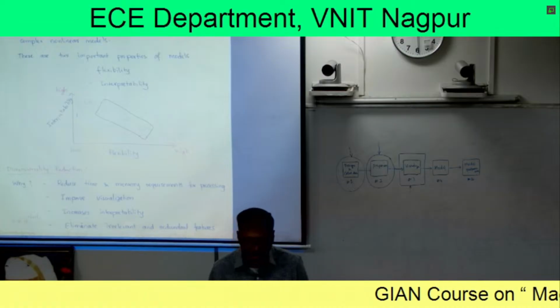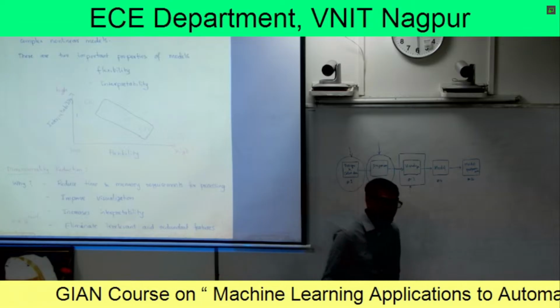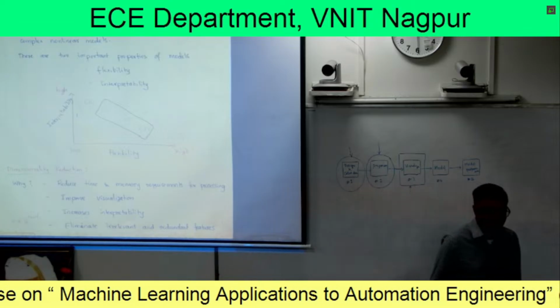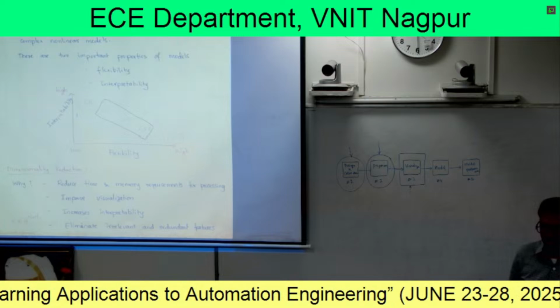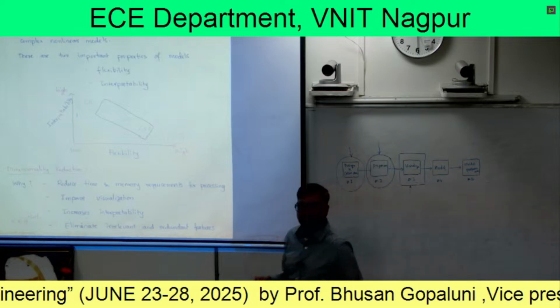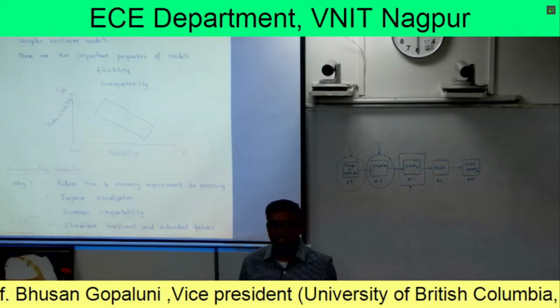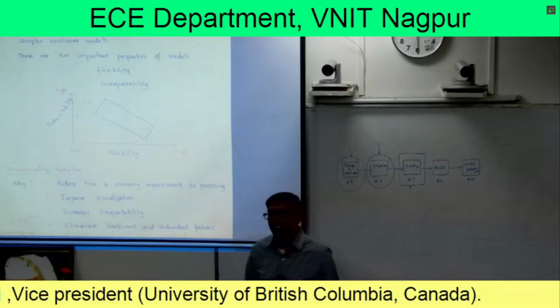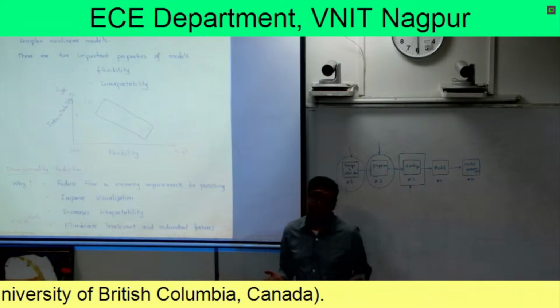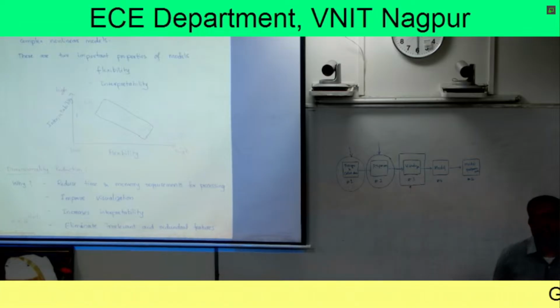If you want a model to design a closed loop controller, not for set point tracking, but for regulatory control, you're probably going to be okay with a simplified data-based first order model. You don't need a complex, high-dimensional, nonlinear model for controlling your system.